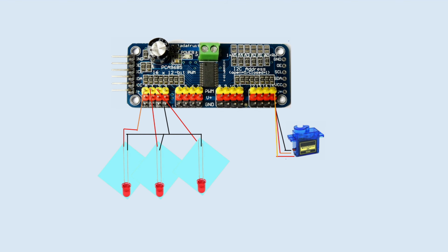All right, so this is kind of just a base rough drawing of what it would look like, and you can do LEDs and servos on the same board. So you've got a servo, it's got 3 wires, and they're typically color-coded, orange, red, black, or white, red, black, and the white would go to the orange or yellow pin. Otherwise, it's pretty simple. The LEDs, from the PWM to the anode positive of the LED.